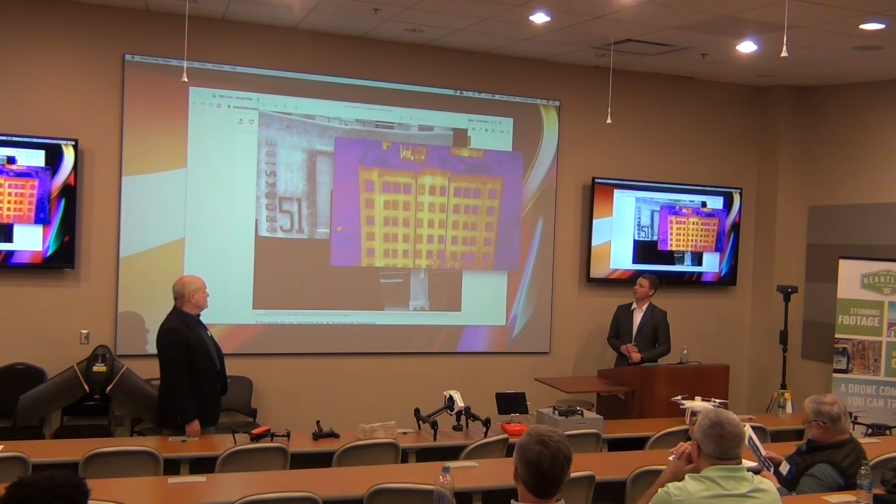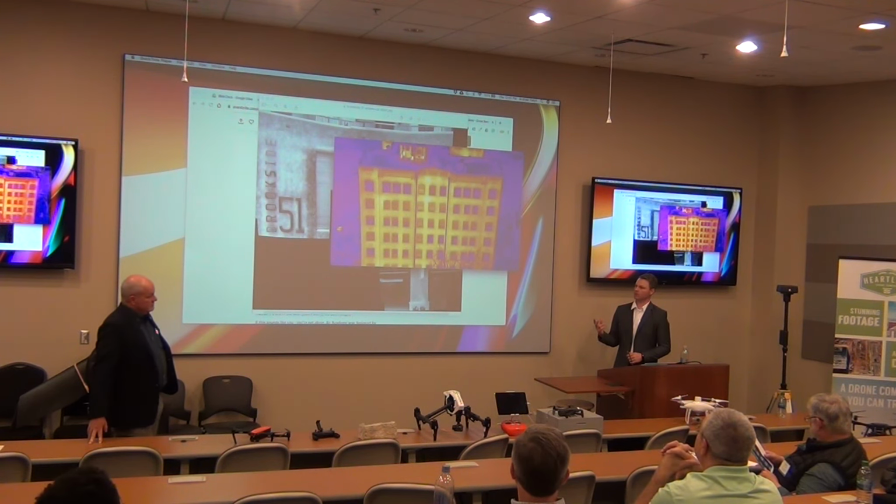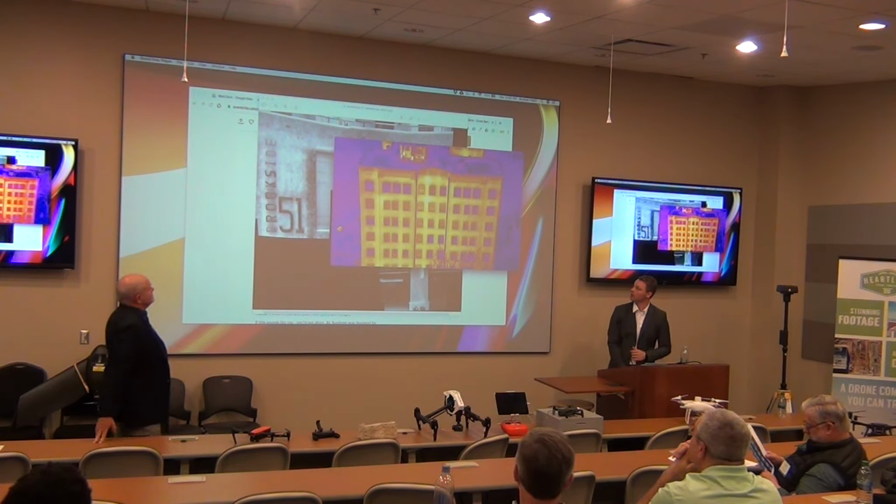And when we were there on site, aside from doing the facade and window inspection, we took a moment to fly the roof. We saw an area on the roof where it was a relatively new roof, right? But we saw some areas of water penetration, and it was actually this spot right up here on the roof, okay?